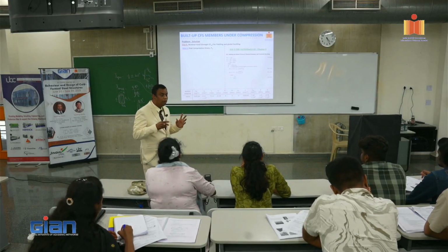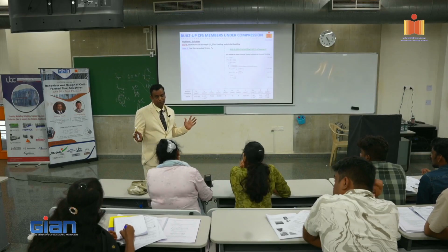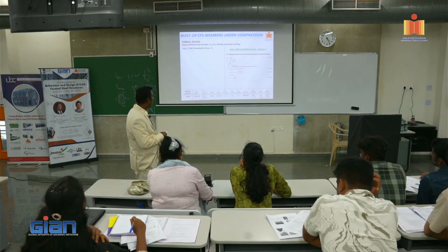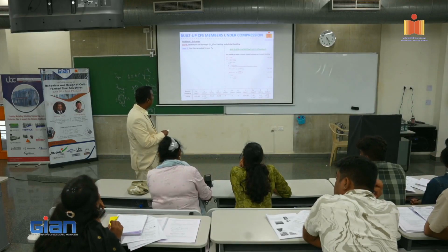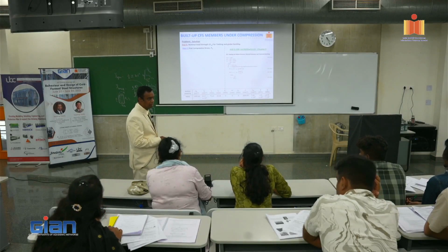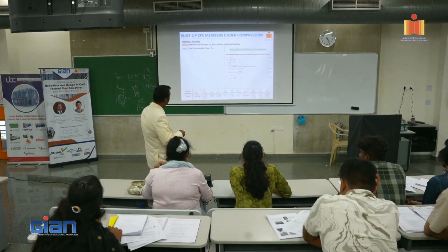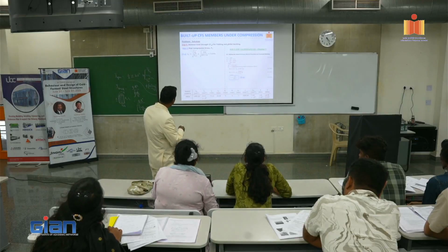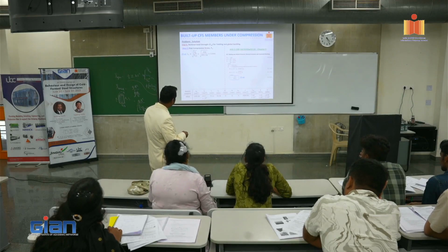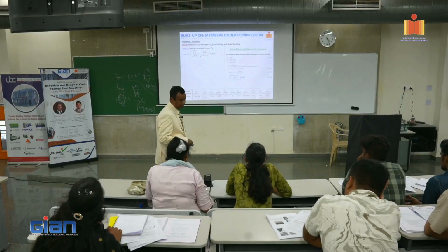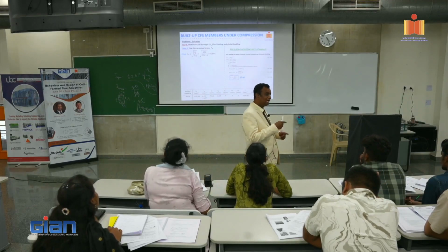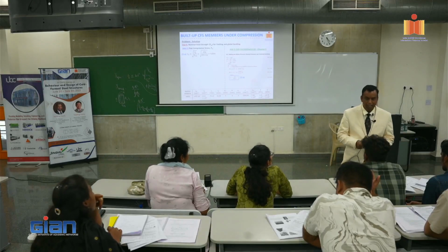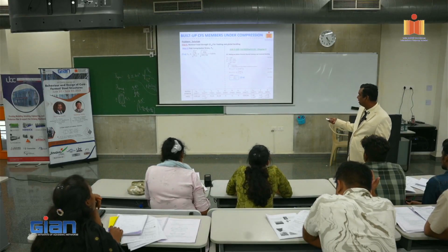Now, I don't know which equation to use. Should I use the top one or should I use the bottom one in order to calculate my PNE, which is AG into Fn? But to know that, I need to know lambda. So that's why I need to use this equation. Lambda sub c is given as root of Fy by FCRE. So in order to arrive at which equation I should use, I should calculate lambda. In order to calculate lambda, I need to have FCRE.